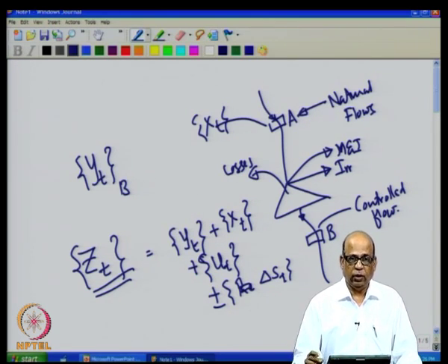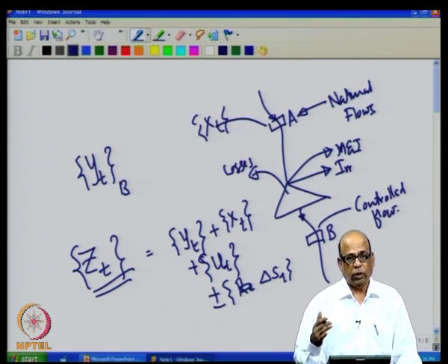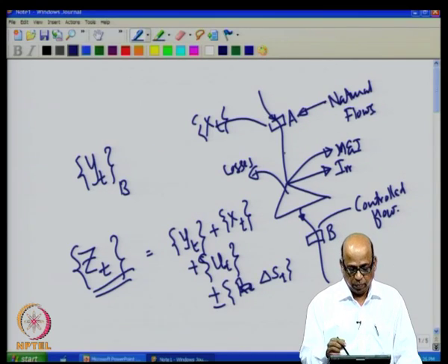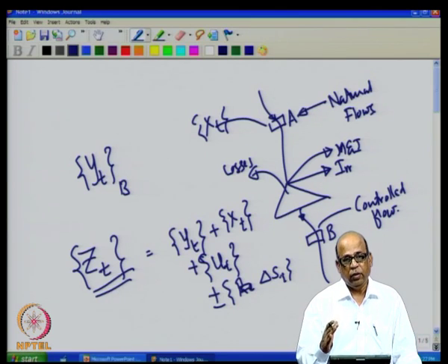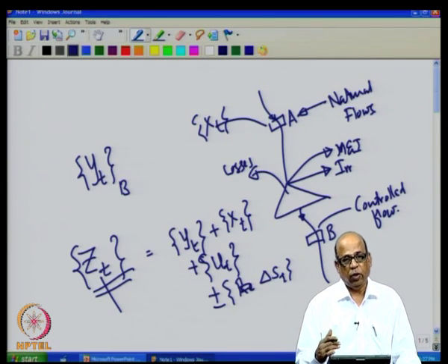Typically, if you are talking about monthly flows, you want to reconstruct the monthly flow sequence here, then do it for 30 years, 40 years, etc. Concurrent data should be available on all the utilizations and the reservoir operating policies that you have adopted, and the gauge flow immediately downstream of this and the storage fluctuations that you have, etc. Reconstruct the sequence and then do all your analysis on ZT here, and ZT will be the reconstructed time series at this particular location, and these are called as the naturalized time series, naturalized flows.